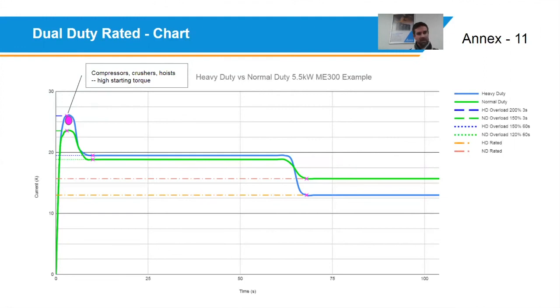But like I said, the typical control layer structure would be SCADA, Ethernet to PLC, and then PLC either CANopen or RS485 or something else to the variable speed drives. That would be my suggestion. Yes, definitely possible. Yes, we've done it before. But starting at SCADA, PLC, and then drives in that format.